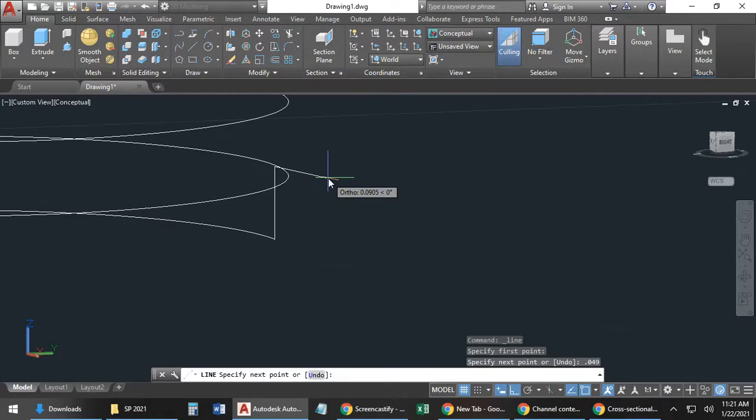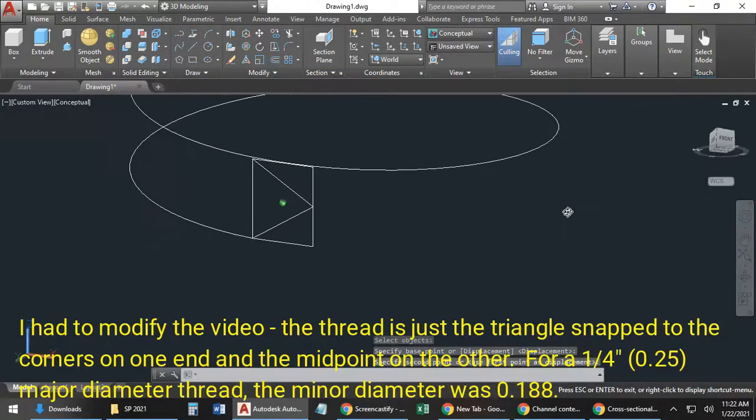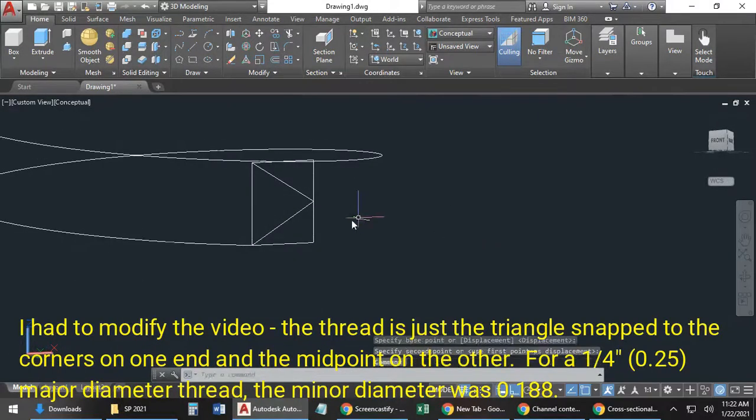There's a chart that tells you how to calculate the height of the thread or the pitch of the thread versus the height versus the depth, all those things. But you can get it pretty close coming out 2/3 or so. So we'll just punch that in at point, I don't know, 3/8. There we go. That looks close enough. So now I'm going to delete these pieces out. I need to join those lines together. Don't forget to join them.